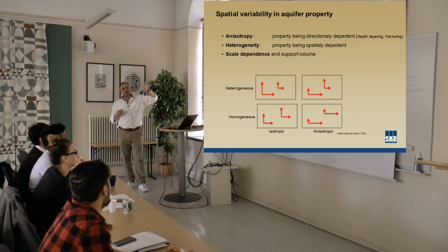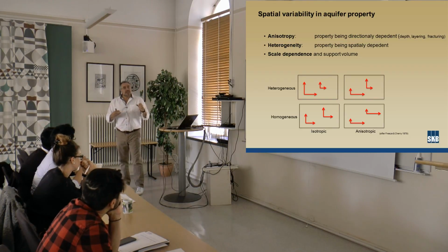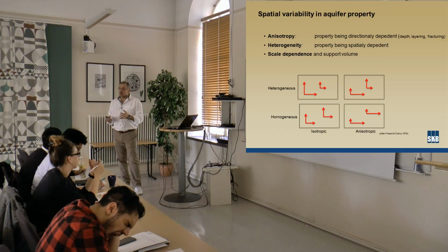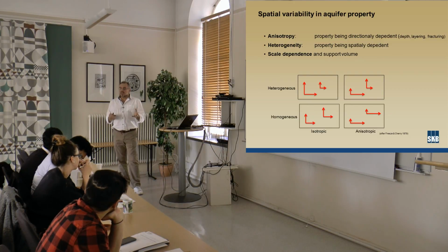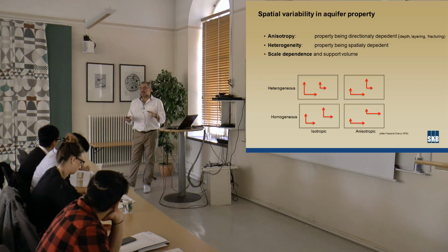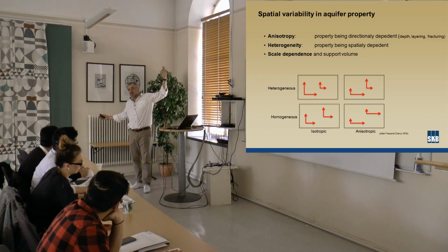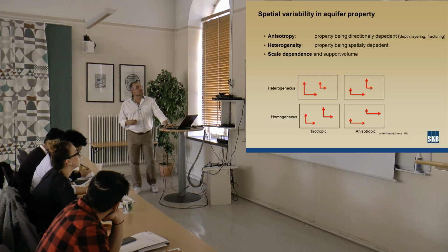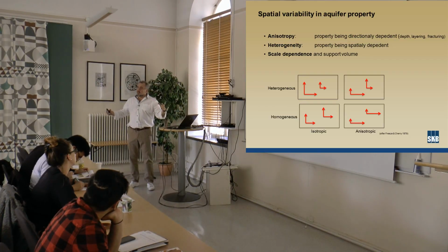The third point here is scale dependence and support volume. So when we make measurements for a certain property, like a storativity or a hydraulic conductivity, we do the measurement with certain equipment, with a certain length scale. And it is absolutely crucial that we are aware of the scale at which the measurement is made, because when we use the data, usually we don't use it at that scale. We discretize our world, the 3D world, into cubes, which are much larger. So there is a scale dependency. If I measure at this scale, I won't get the same answer as if I measure at this scale for the same borehole. So this is an important issue which is being dealt with. And of course, the scale dependency is directly related to the support volume, which is basically the volume of the rock which is supporting, affecting the measurement.